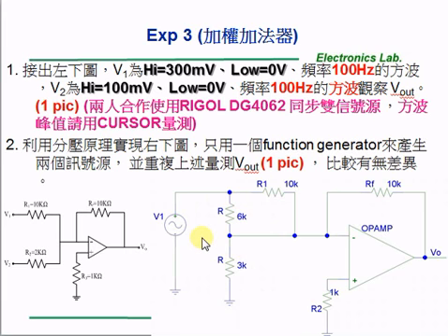While measuring the peak-to-peak voltage of the square wave, use the cursor function. If you use the peak-to-peak function supplied by the oscilloscope, it is very likely that the value is corrupted by the phenomenon called overshoot. So use the cursor function to measure the peak-to-peak voltage.